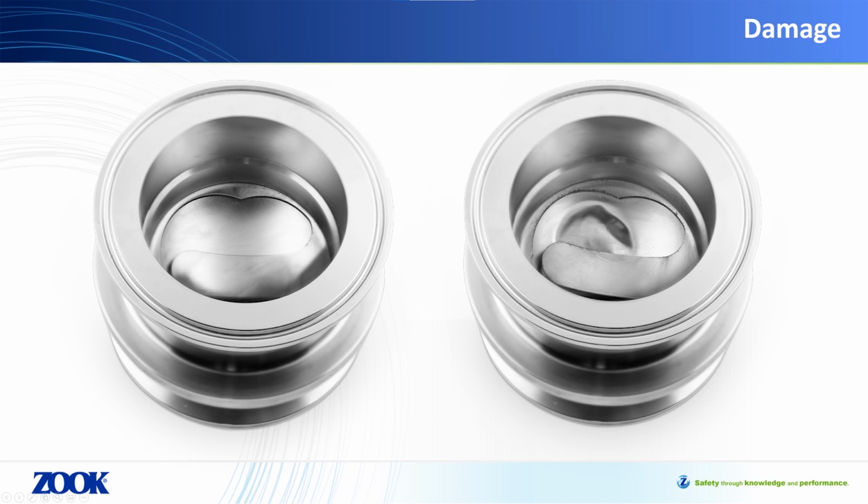All disc manufacturers will take extreme care to fabricate, package, and ship you their discs, but handling in the field is just as critical. Discs should always be handled by their edges or tags, and please never touch the disc dome. Never set the disc down on its dome either. A disc showing signs of damage should not be installed. Disc damage in the field is the single largest cause of rupture disc nuisance bursts. I use the term nuisance burst loosely, and what I mean is a burst at a lower level than marked or expected. These nuisance bursts can still be expensive or result in significant loss of production or time, or both, and they need to be avoided.